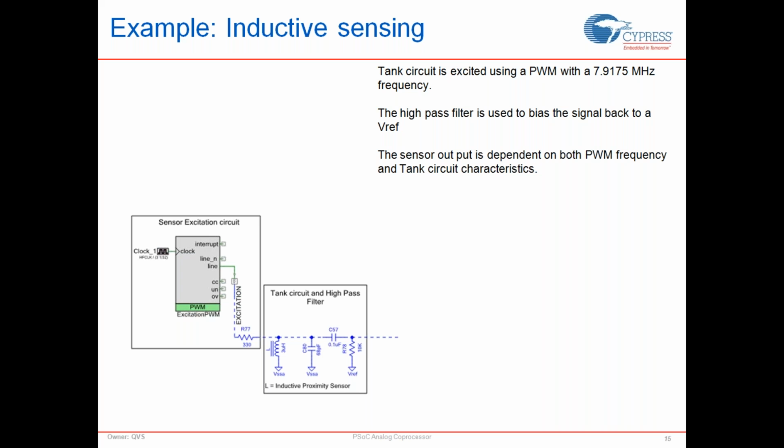Once you build the circuit, you would see that the output signal is already a pseudo sine wave kind of output because you've taken out most of the harmonic content present in the PWM's output. So we're going to have a PWM built using a fractional divider, which is a mode of the input clock dividers where you could configure them to be a fractional division.